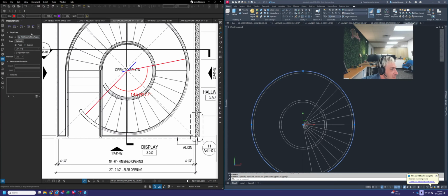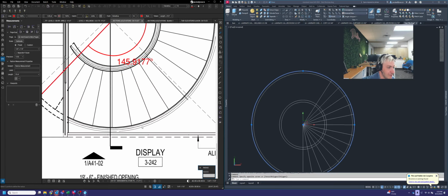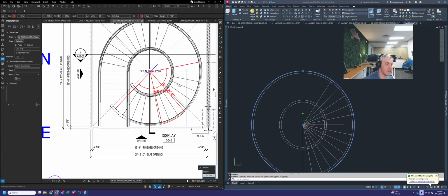So what I did was I could do that center point method and pull a measurement off that center point, but I went to my Bluebeam measurement tools, and I know there's a radius one that's here, but it's terrible. There's one here if you click on the arrow next to it, that's a 3 point radius though. And if you use that, you can just click on 3 points on a curve and it will actually calculate the radius based on those 3 points.